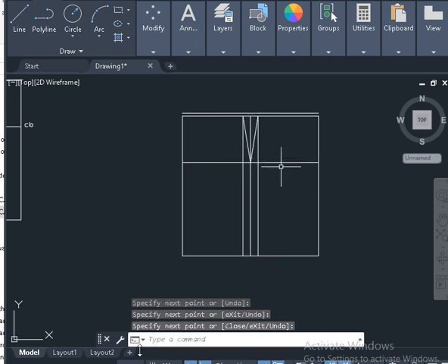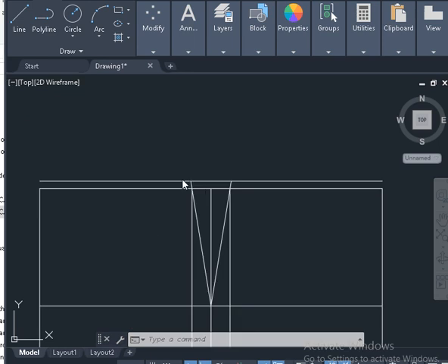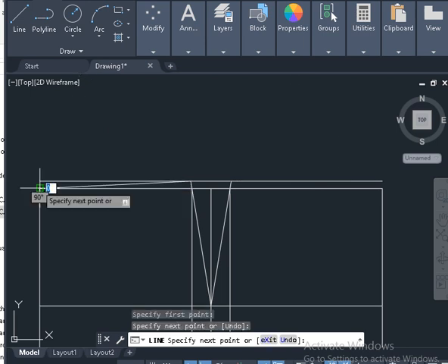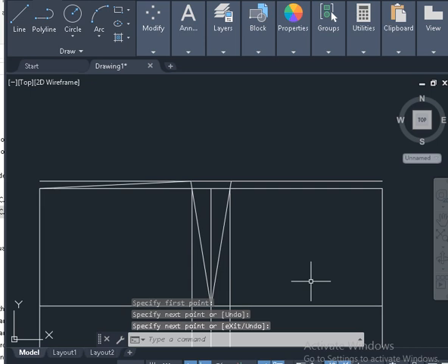And then once we've done that, we extend those lines so that they touch that 1.25 line that we've drawn at the top. You just type extend on the command line so that you'll be able to extend there. Right, once we have extended these lines to touch this line, we also join those lines with our blocks. Just join the lines from the side to the center front. Go to the center front, and we also do the same there in the front there.